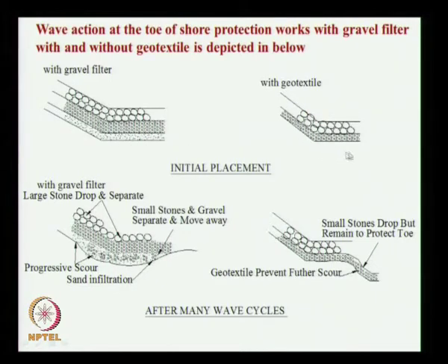Here we have not shown the bed material, but bed material exists here, but there is a filter fabric here, below that we have the seabed material. So this is the seabed material, this is the core material, this is the armor stone. So the seabed material and core material there is no filter fabric, so this material can go down, this material can go up. So whole thing get mixed here. The small stones and gravel separate and move away, and the large stone drop, these stones also will drop and they also will separate, then we will have a progressive cover and sand infiltration also will take place.